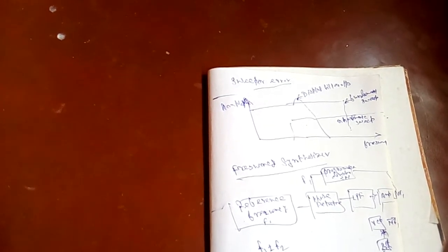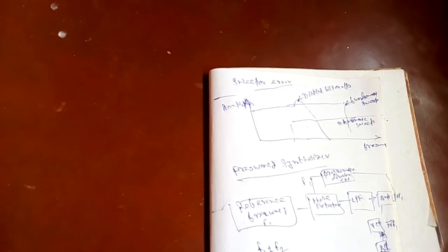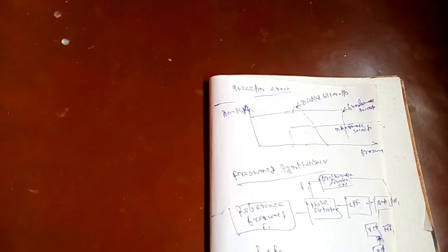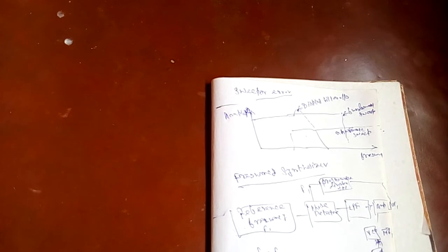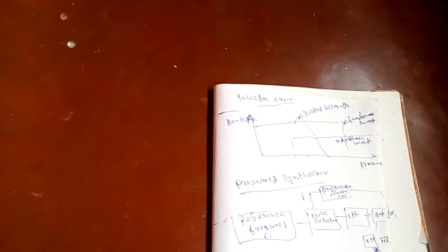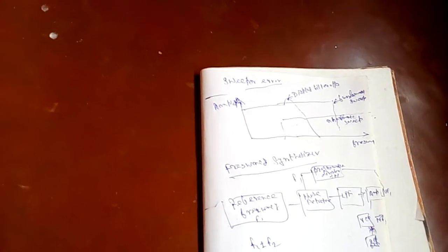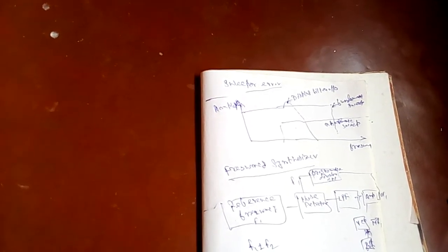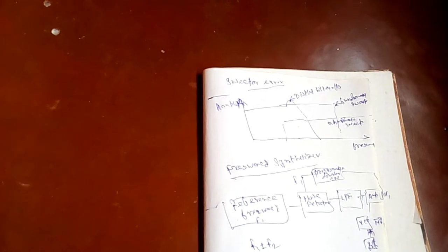The output of the VCO is then passed to the programmable divider and back to the phase detector, so that the system pulls F2 toward F1 until they are equal, and at that stage the phase difference between the two frequencies produces sufficient DC signal to keep F2 locked with F1. The output frequency is N F1 and is changed by changing N, usually from the keyboard on the front of the instrument. The switching speed of the frequency synthesizer depends on the time needed for F2 to lock to F1